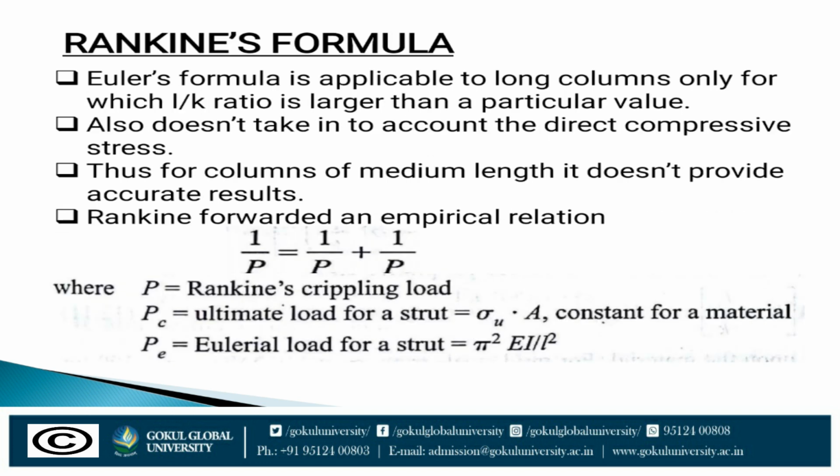Next one is Rankine formula. Euler's formula is applicable to long columns only, for which the L by K ratio is larger than a particular value. It also does not take into account the direct compressive stress. Thus, for columns of medium length it does not provide accurate results.